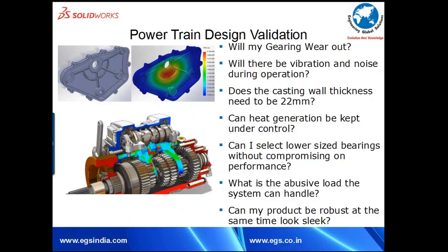The Germans would take 65 millimeters as the LMC condition and would build up the tolerances unilaterally on the other side because they are confident of their designs as compared to us. This was a statement made by one of the design engineers, a designer, an owner of a company who had more than 35 years of experience in design.